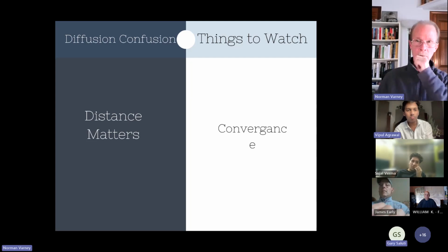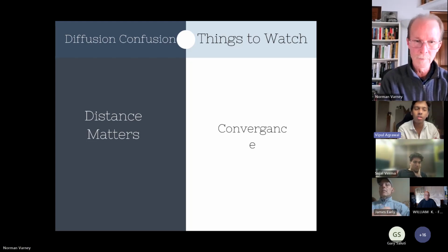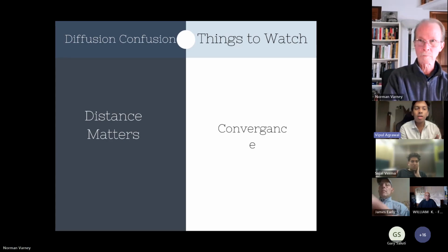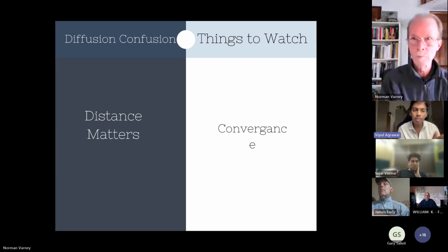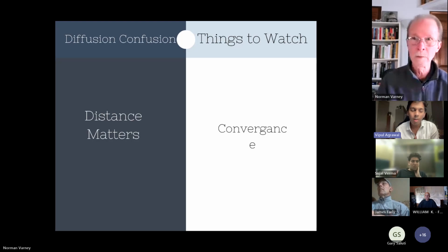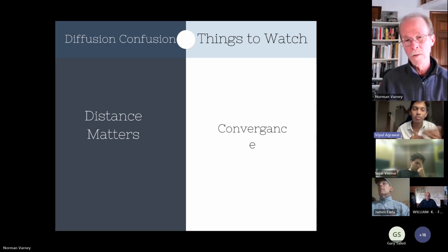Okay, so basically, in case you're not aware, non-environmental is Tom Hidley's approach of designing control rooms, in a way where the entire room is controlled with absorption only, right? I personally like to do it that way, and I would like to receive your input on it, Norman. If we use diffusers in a way that they are placed and designed for a certain bandwidth, feeding reflections after a certain time frame, kind of like LEDE. LEDE uses the Haas effect to envelop the listening position, but in a more subtle way, so the reflection is not really measurable on the ETC, right? But like an amorphous reflection. What do you think about it?